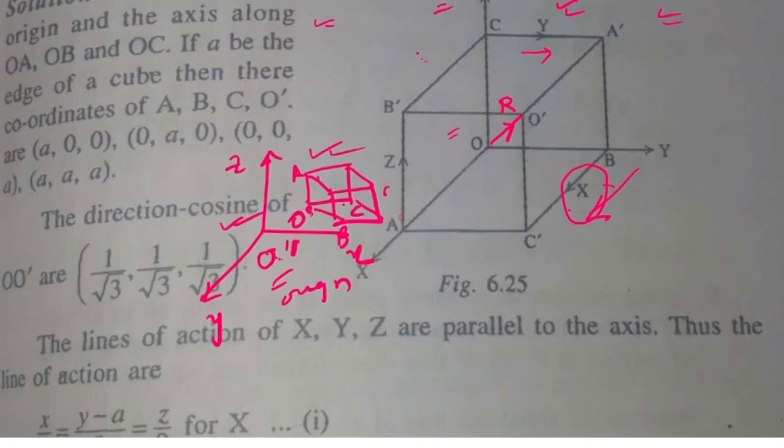So we just choose the easiest way and we have fixed this as the origin, because once you are measuring all these things, one thing we have to satisfy: whatever base system you are applying, that should not change within your calculations, right? That means once you calculate one force taking this as origin, for calculation of another force you should not take some other point as origin. If that is the case, then we need to be careful. But here the cube is not moving, it's fixed, right? So we need to take care only of the geometry of the cube, no motion of the cube.